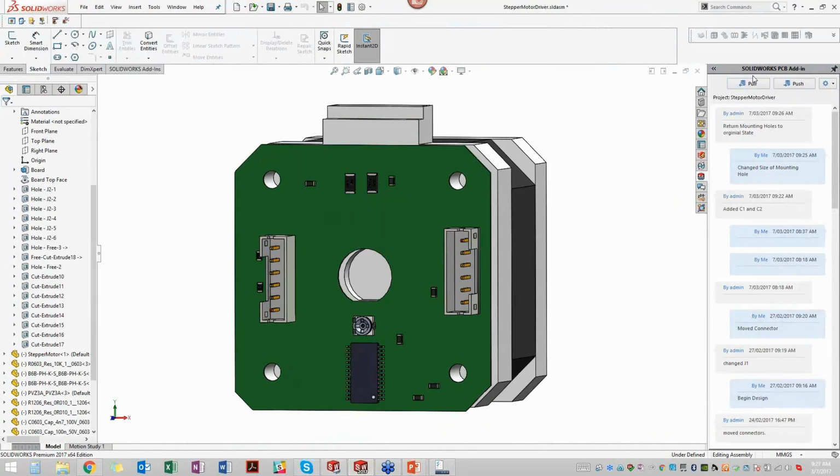And they'll go through and they'll create a new project for the Altium team or for the SolidWorks PCB team. They'll create a new board outline, a board shape, and put some mounting holes in it. And they'll push that over to the electronics people. And that way, when they start their design, they already have a board outline started to be specifically what they wanted. And it was native to what they're working on. They didn't have to do any file translations or anything like that.